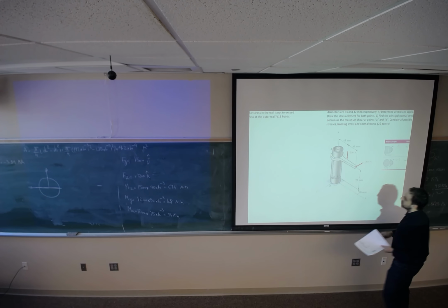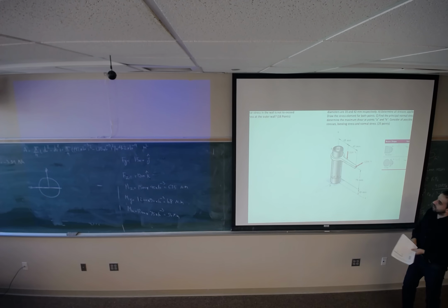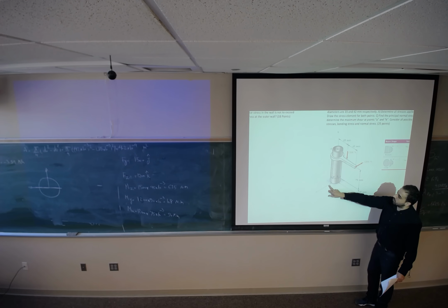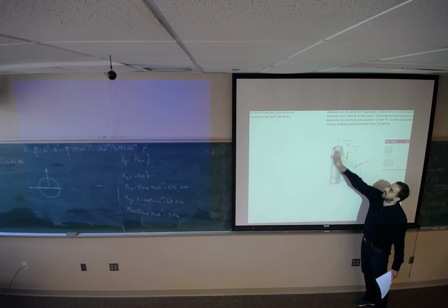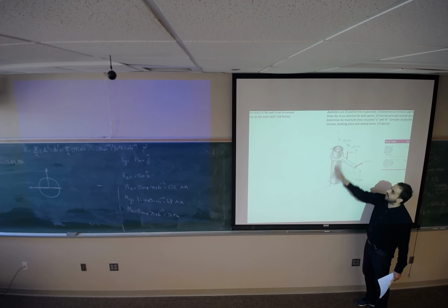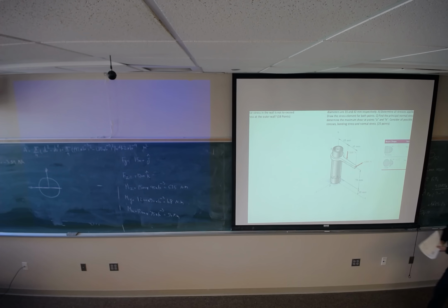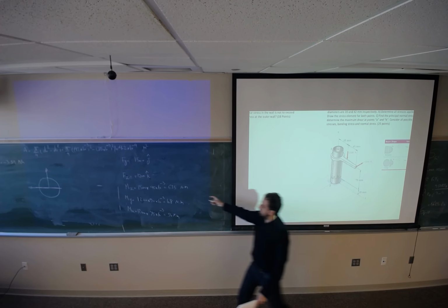So bending moment about z-axis. So it's rotating about z-axis. If bending moment is about z-axis, the neutral axis is gonna be here. So point A is gonna be there. So it's not gonna see any normal stress due to the MZ. So I shouldn't be worried about this.